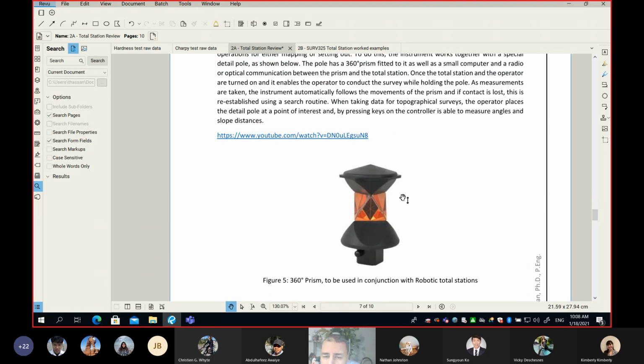Just to remind you, I'm not going to go through the videos one more time. Bottom line is, no matter what type of total station, no matter how advanced your total station is, backside is required. And measuring the instrument height and reflector height is still required.